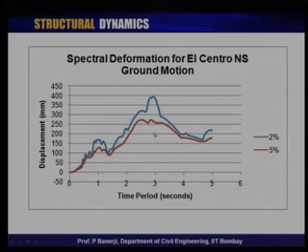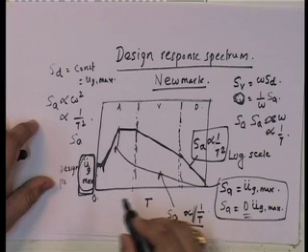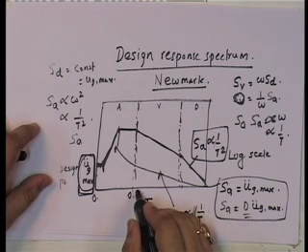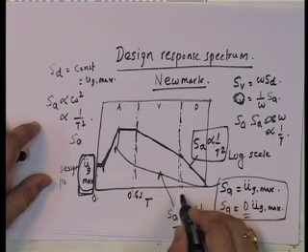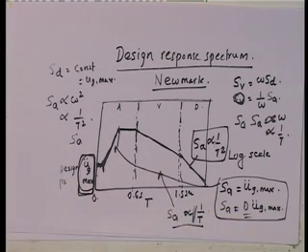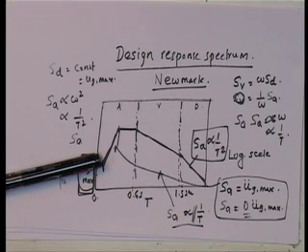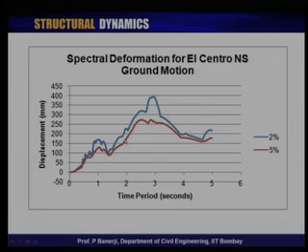Okay. And so, in this particular case, we can almost say that this goes from 0 to about 0.6 seconds. This goes to about 1.5 seconds. So, approximately this is what we see, right. Spectral displacement from about 1.5, 1.6 seconds is where displacement starts controlling.